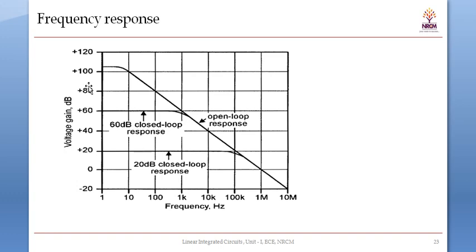like resistors and capacitors, and with the help of this resistor and capacitor network you are modifying the rate of change of gain and phase shift, and this network of resistor and capacitor components is called a compensating network.